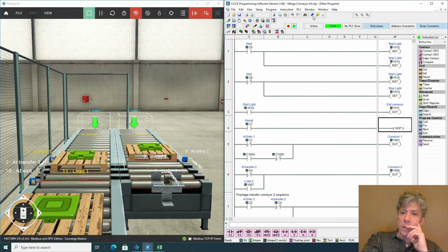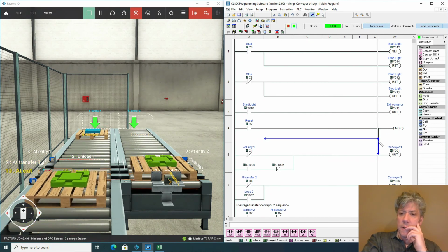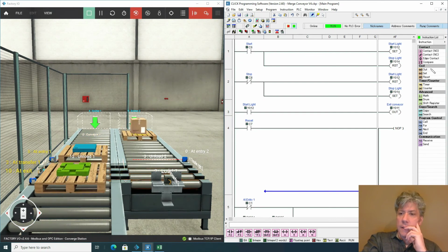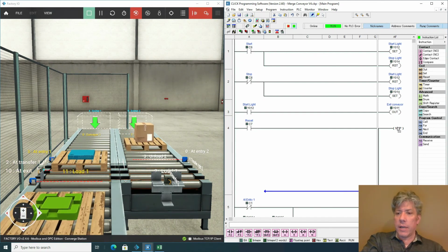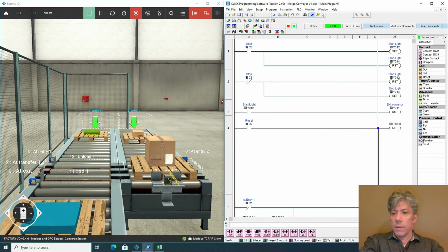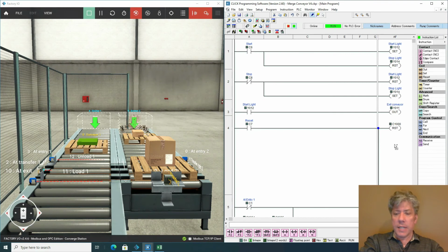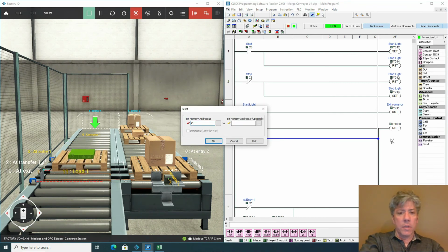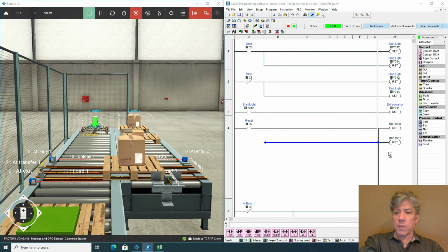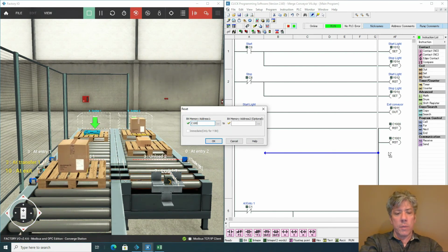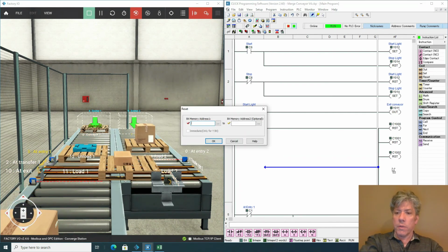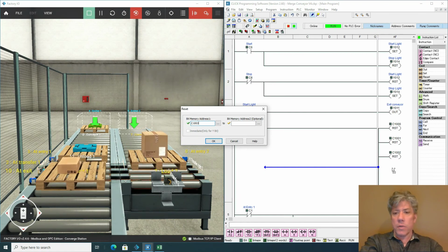So all I will do is make a whole bunch of resets here. I don't know how many I need. I mean, I know I need, what, 6? C1000, but I didn't count how many lines I was drawing. C1001 all the way through 5, so since we started from 0, it's going to be 6 different reset instructions. For C1002, another reset, C1003,